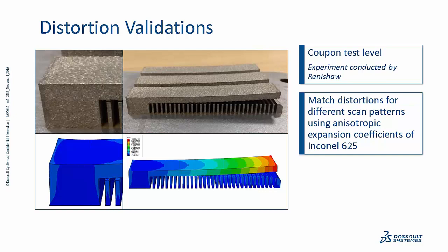This is a PBF, or powder bed fusion process validation, a joint work with Renishaw. We simulated virtually the printing process of the Renishaw bridge models, including different scan path strategies using Inconel 625. Thermal strains were computed driven by the temperature history predicted firstly through heat transfer analysis. We have accurate quantitative prediction of the distortions for 0 and 90-degree scan strategies. And based on physically homogenized thermal expansion coefficients, our prediction for rotating 67-degree scan strategy is also very close to physical measurement. Besides, we are able to capture the shrinkage in the anchor next to the edges, same as observed in the experiment.